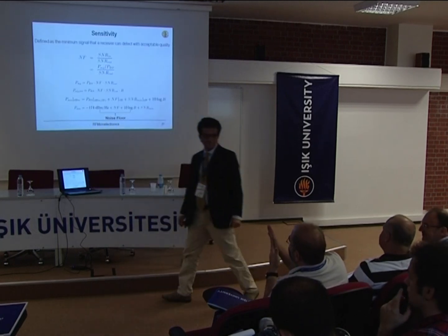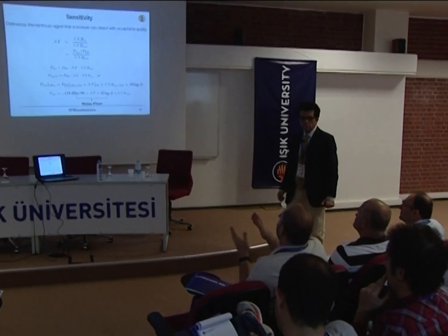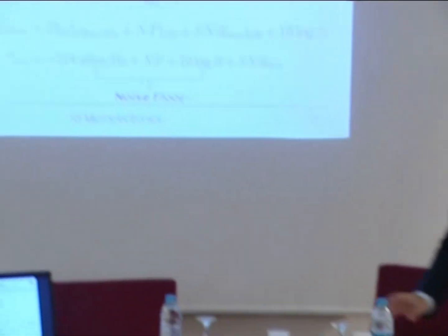Well, for this noise floor, we have one fundamental limitation. We cannot go below -174 dBm. Yes. And of course, it is because of the 50 ohm standards that we use in the measurement equipment or electronic equipment. Do you see any possibility to decrease it, for lowering this noise floor even further?